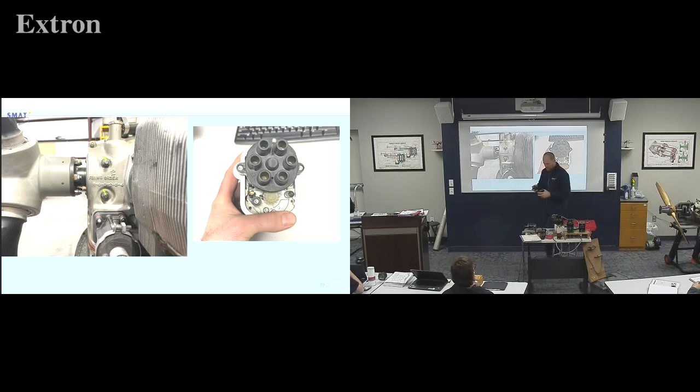So what happens with magnetos is if I look at it and it says left hand, here we go, this one's a right, yeah, we can confirm, good, I'm correct. That's all I had to do was find one that has an impulse, because if I go the wrong direction, no impulse. If I go the correct direction, the impulse works. So, looking at it, what happens is in that gearing, it reverses the rotation.